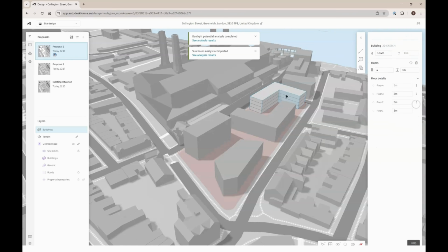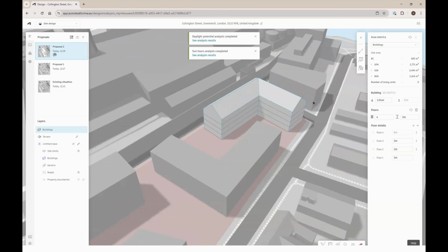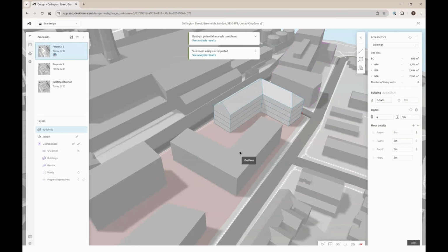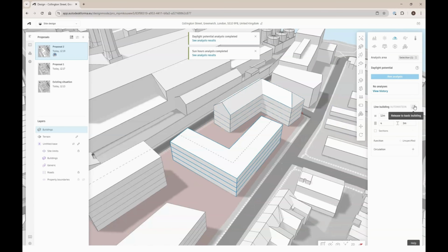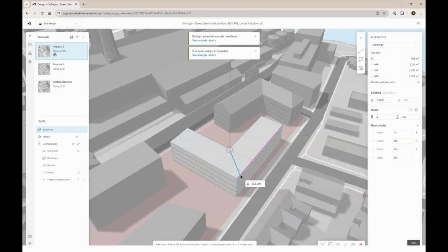So I'm going to open the building in 3D Sketch, which works similar to SketchUp in the sense that it works with faces, and you can push, pull, and create lines and such. But it's very powerful in its smartness. So for this case, I'm just going to pull it back a little bit more. And as you can see, it's quite responsive, and you can show your intention quite a lot faster.